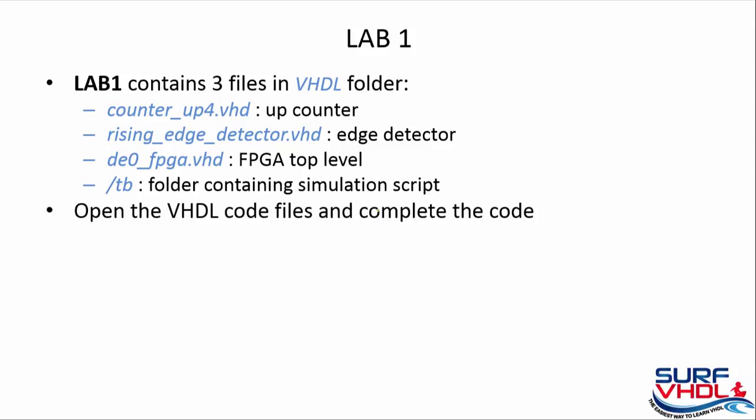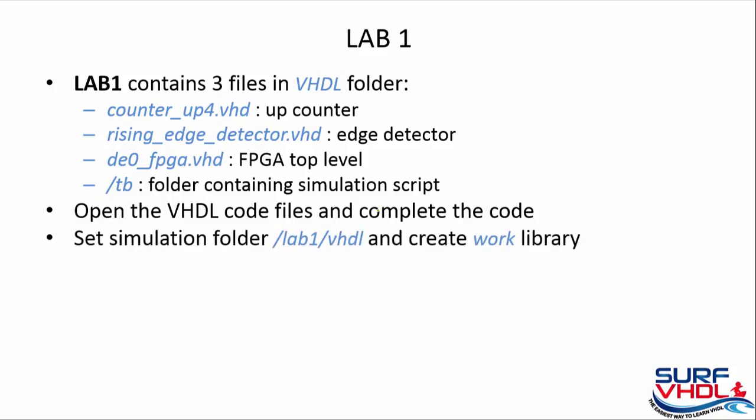So you need to open the VHDL file and complete the code where you find insert your code here. Set the simulation folder as lab1/VHDL and create the library work.